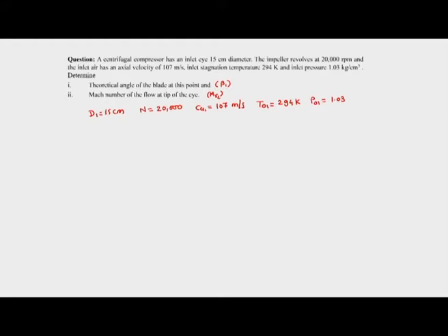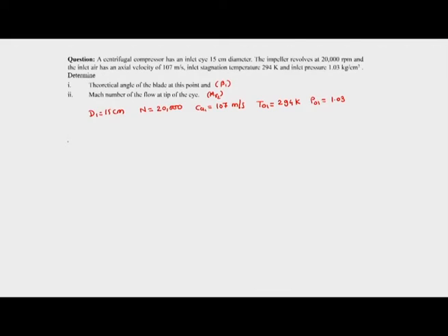So now for this, let us see what is given to us. We know the velocity triangle for the centrifugal compressor at the inlet: this is our CA1, this is U1, so we have this as V1. So this is our velocity triangle. So we have alpha as 90 degree and we have beta 1. So this is known to us.